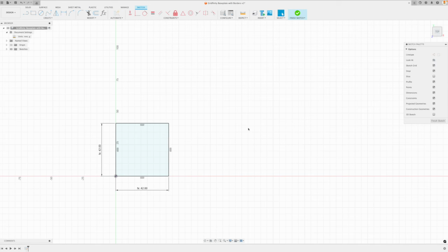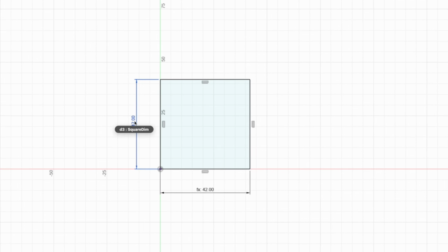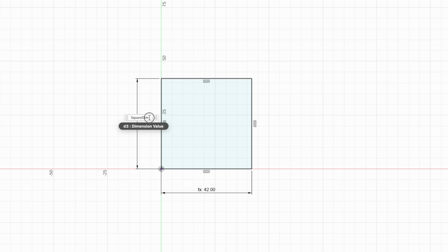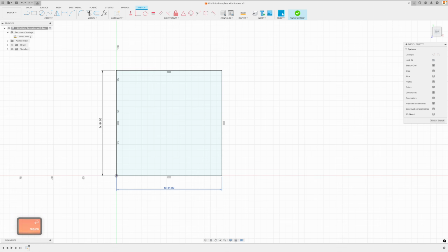Let's go OK. And remember, with an Excel spreadsheet or standard spreadsheets, columns go up and down, and rows go left and right. So if we go to this parameter right here, let's go square dimension times, and we'll type in rows and enter. And then over here, we're going to do the same thing, times columns. And we use the asterisk or shift 8 for the multiplication symbol.